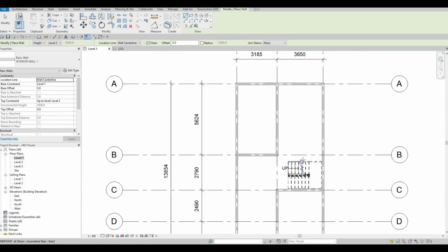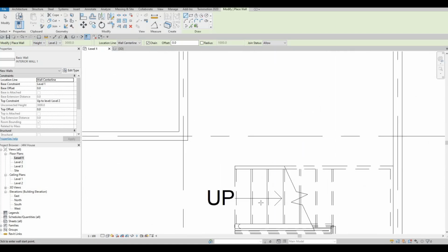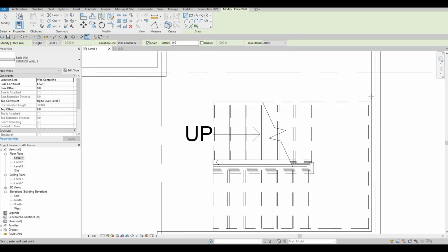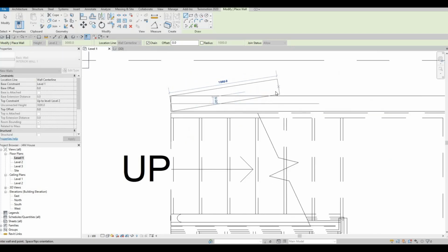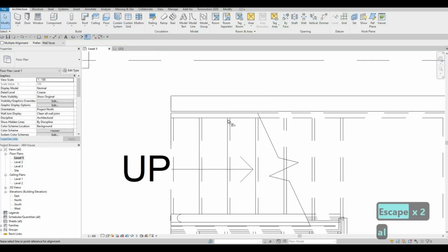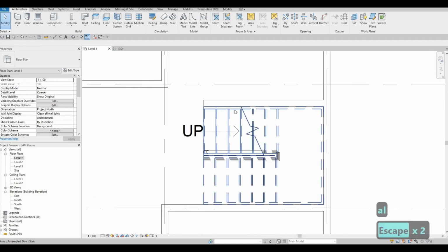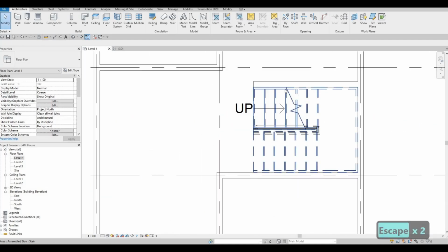So that's something useful to use. So now, knowing that I select the interior wall, I type in CS, and then now I could add it instantly. So now I'm gonna add that right there, AL to align it, and then there we go. That looks much better.